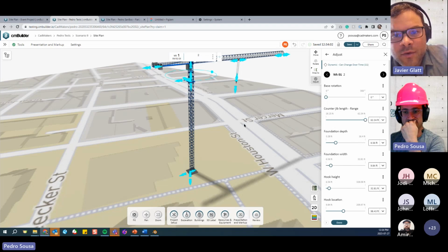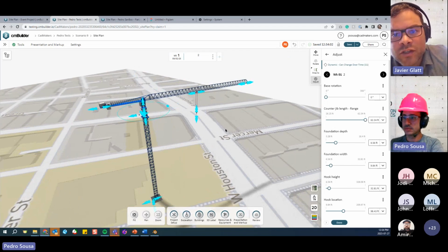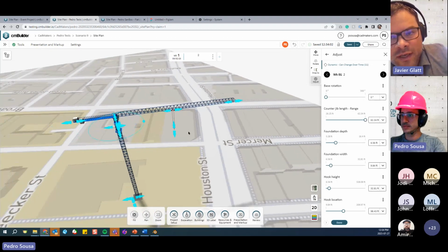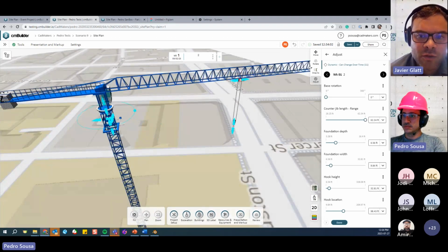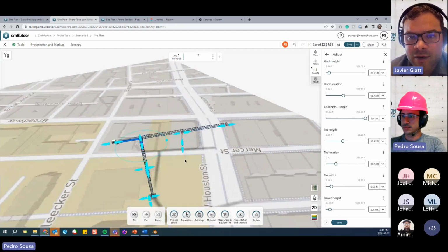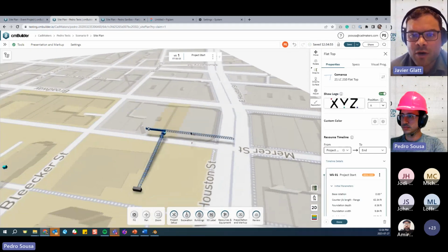So some of the resources that make the most sense, we tried hard, will be set as constant. Things that you likely don't move much throughout the job should be set as constant. Things like cars that drive and cranes that move are dynamic, and you want to set them to dynamic so that you can show those animations, with different positions throughout the simulation. Most of it is based on that and other use cases that I've come across.